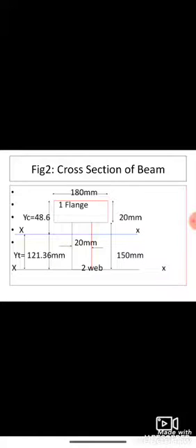The figure is given, simply supported with UDL on entire span. UDL W is equal to 80 kN. Next, this is the cross section. First of all, to understand, this is a T section. The top part is flange number 1, so its width is 180 and depth 20. Then below is its web, width 20 mm and depth D2 is equal to 150 mm.